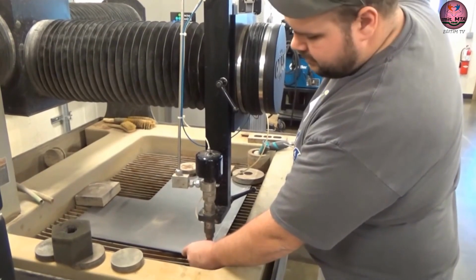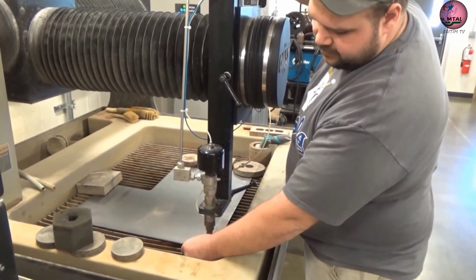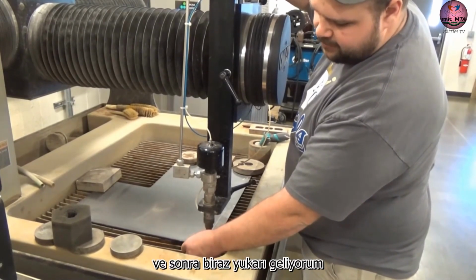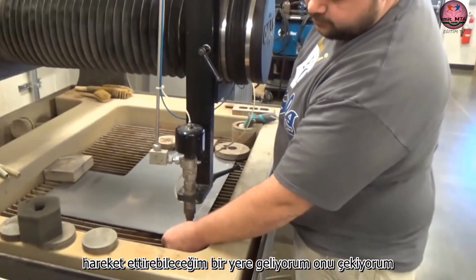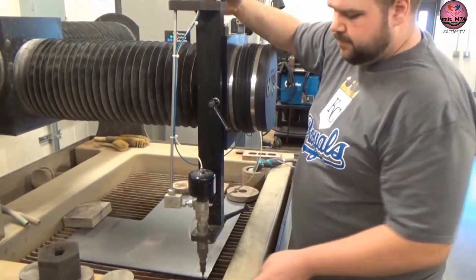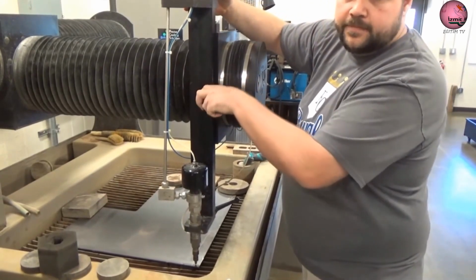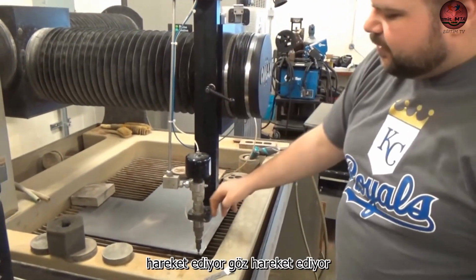It's not super critical. I usually go down to it until I can't move it, and then I come up a little bit, to where I can move it, pull it out, and then just maybe an eighth of a turn farther higher up. And then you're going to turn this handle to lock it in position, and this is your Z-axis, moving your eye.